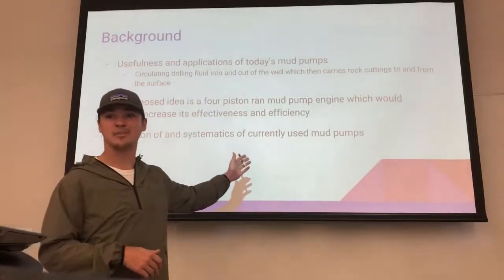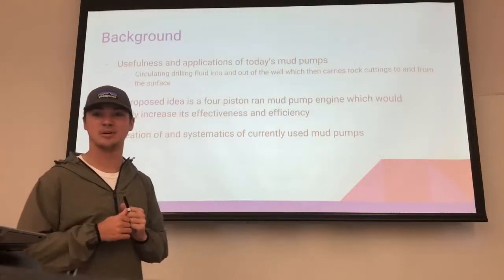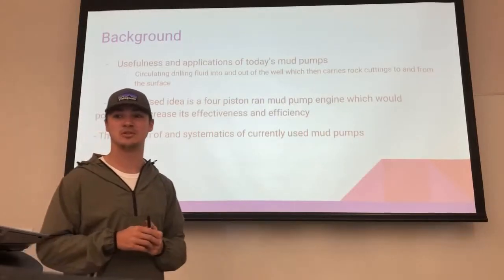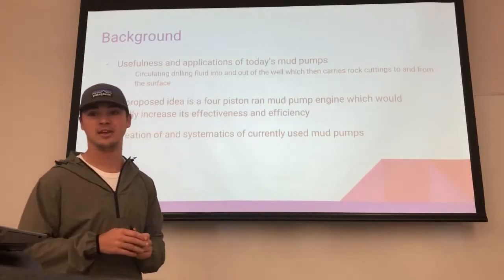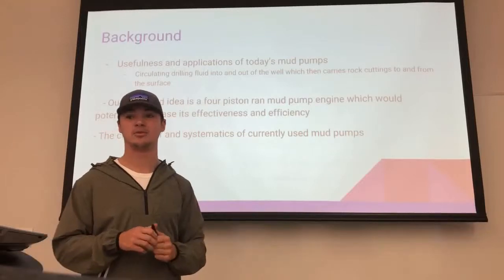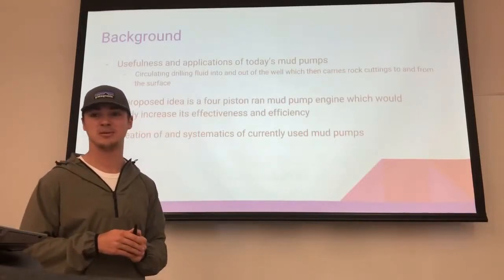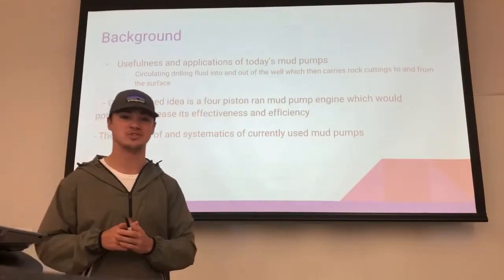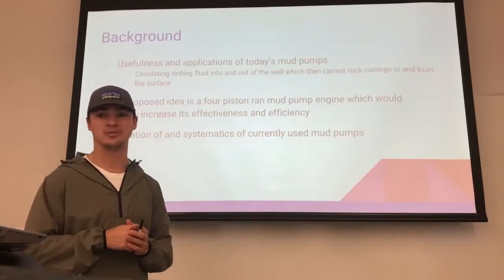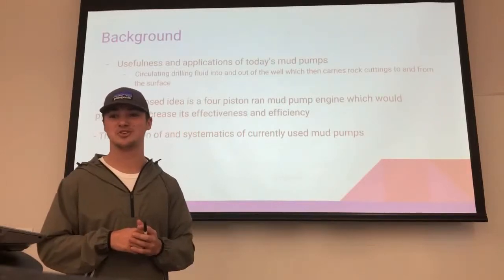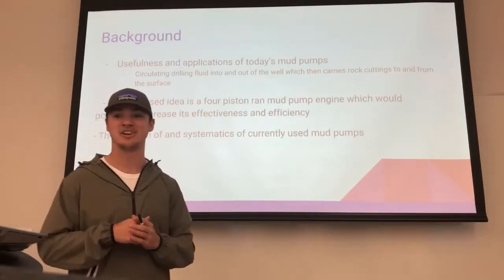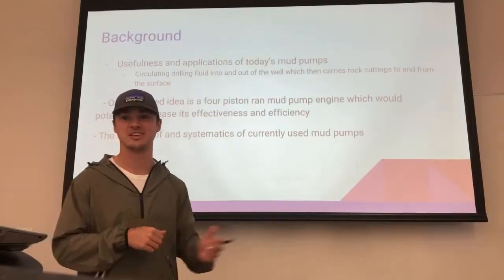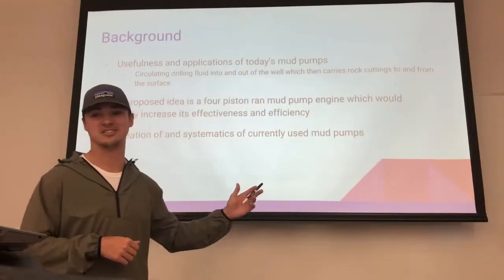More background about the applications of today's mud pumps is that they pump drilling fluid down into the well through the drill pipes and release it through the drill bit at the bottom of the hole, then it flows back up to the surface with valuable ingredients such as rock cuttings, which give the petroleum engineers knowledge and information about the formation in which they are drilling. They are also able to control the rate at which drilling fluids are circulated down the drill pipes, and for instance, at times such as kicks, it's very important to regulate the rate of circulation to avoid undesired consequences.